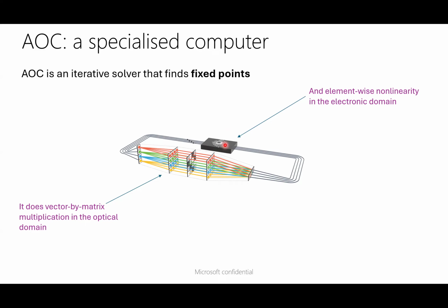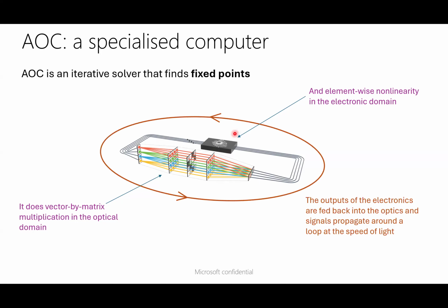And that's not really compatible with our aim to be energy efficient. So in this case here, you'd have 4 output elements which are going round then through the nonlinearity electronically, and then they get converted back to driving signals for light sources, and then signals propagate around this loop. And the signals propagate around in our system unclocked and at the speed of light effectively.